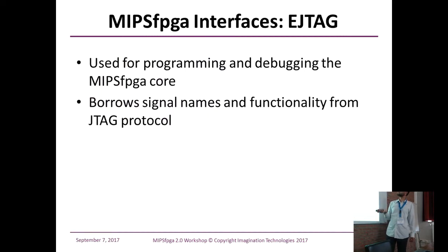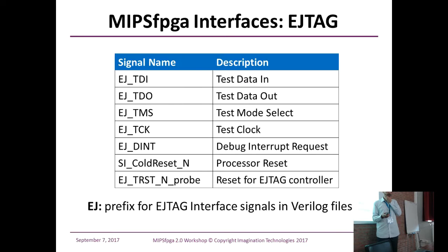So yes, EJTAG, as I mentioned, the signal names are parallel with the JTAG standard interface. We call it EJTAG for subtle reasons. There's not that much different in terms of our use at the moment. So yeah, the signals are prefixed with EJ, test data in, test data out, test mode select, test clock. You can use it to teach EJTAG if you want. That's a whole separate category. What we use, we just basically use JTAG instead of teaching about JTAG much.